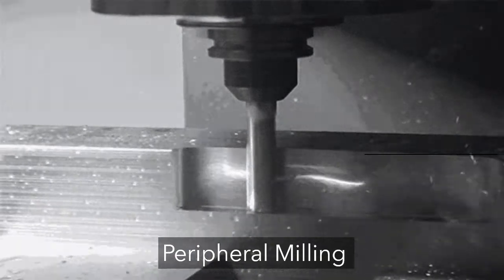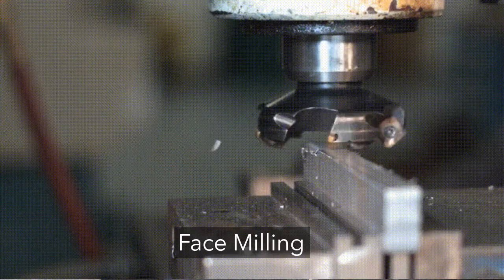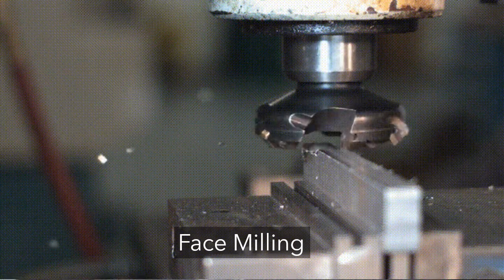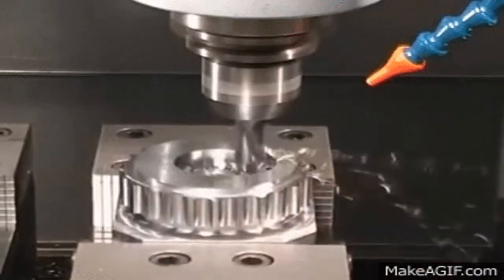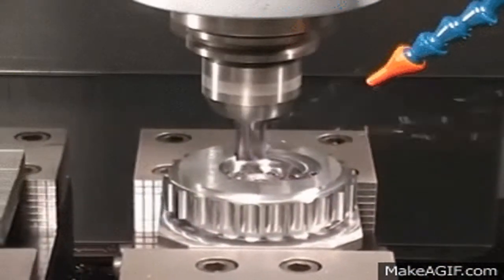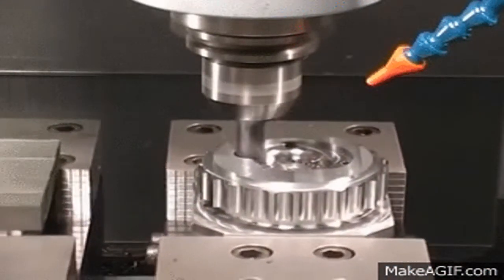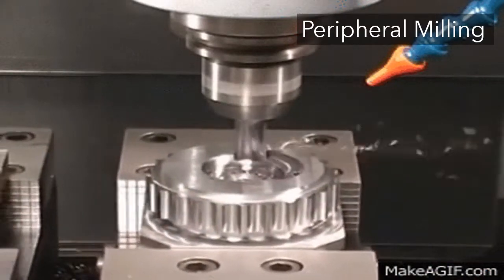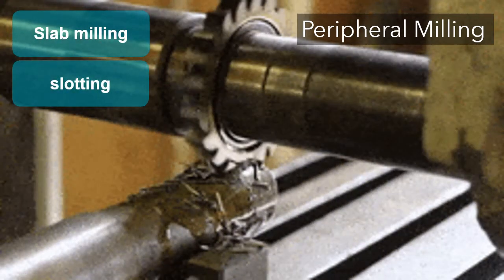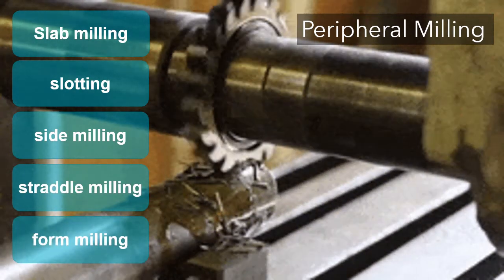There are two basic types of milling operations. The first one is peripheral milling, and the second one is face milling. Most milling operations create geometry by generating the shape. In peripheral milling, also called plane milling, the axis of the tool is parallel to the surface being machined, and this operation is performed by the cutting edges on the outside periphery of the cutter. Several types of peripheral milling are slab milling, slotting, side milling, straddle milling, and form milling.